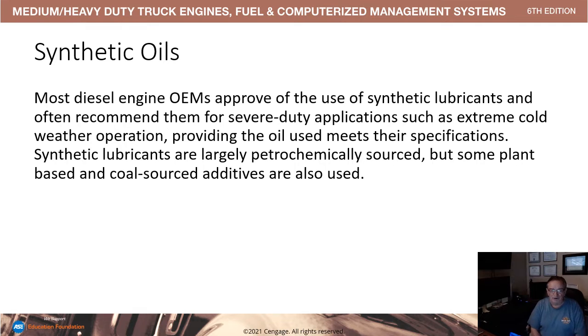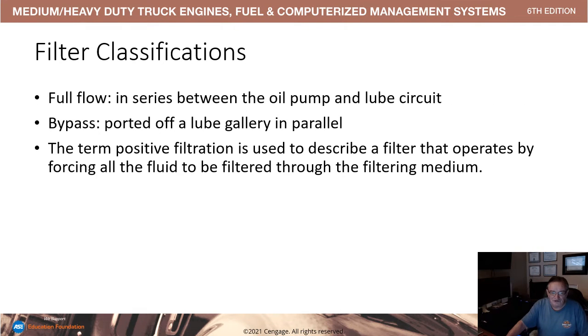Synthetic oils: most diesel engine OEMs approve synthetic lubricants and recommend them in severe duty, such as extreme cold weather operations. Full flow filtration is in series between the oil pump and the lube circuit. Bypass filtration is off a lube gallery, in parallel.